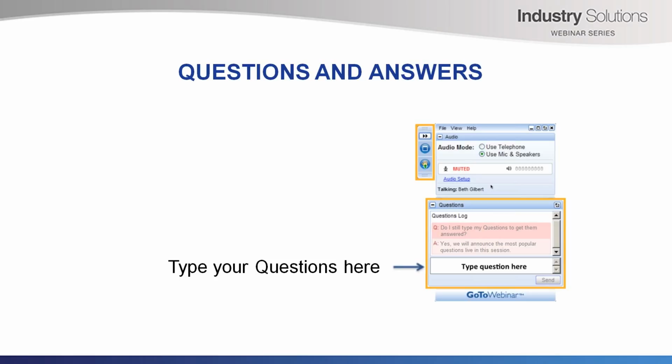Craig in Adelaide asked, does the global ID change for each IFC export? This is an interesting thing, the global ID. Some packages use it as a unique reference, but for that you then have to set it, and it doesn't change. The global ID can change. It's supposed to be unique in space and time. And that's one thing we're just having to look at, that for some packages you set it once and you have to keep it forevermore because they don't think the object changes.